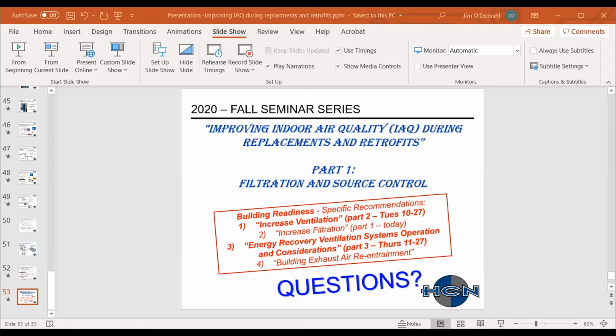where it's still considered to be an electronic air cleaner. But I think the question is that they're saying just generally MERV 13 filters achieve this by being electrostatically charged, not meaning any system that we're talking about here. I think that's why there are electrostatic filtrations out there. I think the filter media being produced by the filter manufacturers, I don't think those are electronically charged. I think a MERV 13 filter is a MERV filter, and it's not achieved with electrostatic charging.